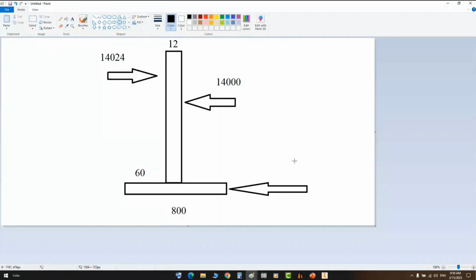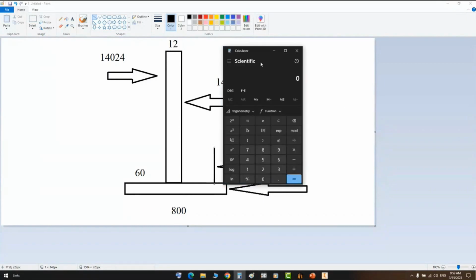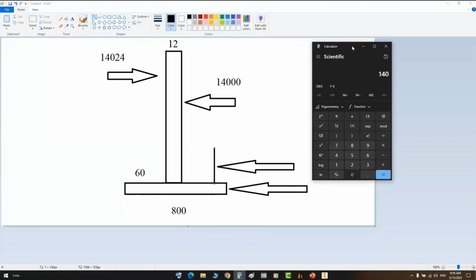After that, we need to calculate the same radius plus 50 millimeters on each side as overlap with the annular plate. So to calculate that, that's the inside diameter plus twice the thickness plus twice the annular plate projection. So here we have the outside diameter of the annular plate.